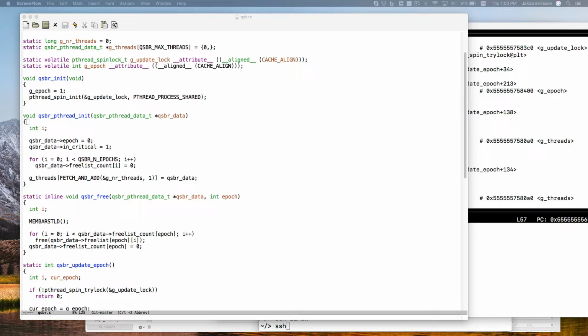If you have a specific memory location in mind, then there's something called a watchpoint. It's not a breakpoint, it's a watchpoint. It's hardware supported, where you tell the CPU that anytime you access this address, it should raise an interrupt. That can be really useful, but in this case, there's lots and lots of these allocations. They're all over the place. We don't know which one's going to fail, so it would be hard to use a watchpoint, I think.